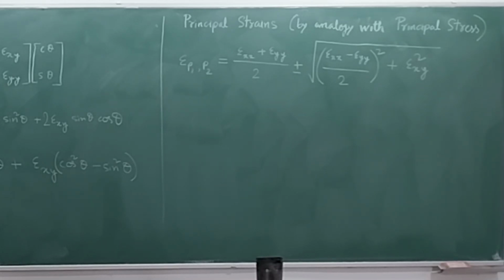And if the resistance changes and it is part of a Wheatstone bridge, then you can actually measure the voltage that is indicated on the dial. So in a very, very indirect fashion, we can find out the strains in the body, and from that we can find out the stresses in the body. Now, whatever I have said may sound like mumbo jumbo to you, but I just wanted to give you a very brief introduction. Later on, when you do the lab, we will spend almost 1.5 hours doing this only. We may also ask you to do the circuit yourself.